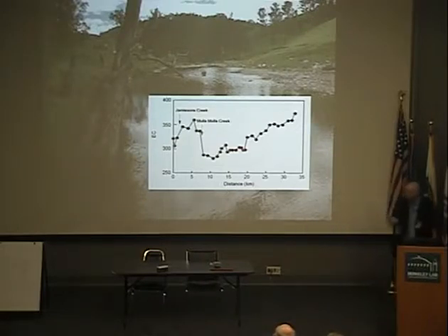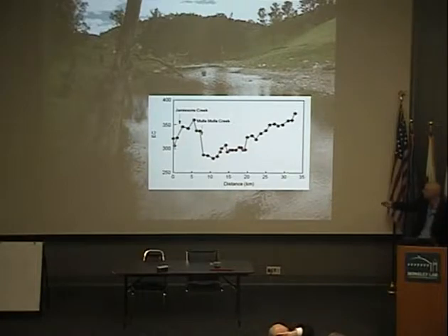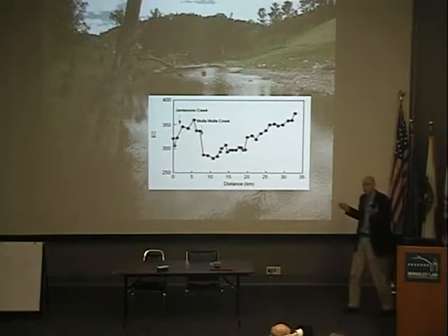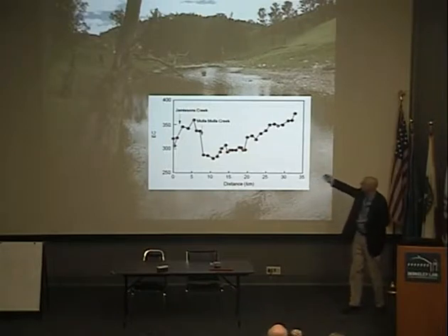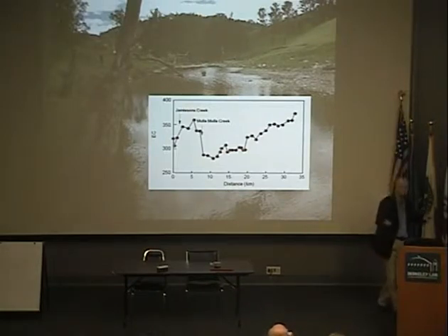This is the Cockburn River again, and this just shows the electrical conductivity in microsiemens per centimetre versus distance. There are a couple of dramatic changes where tributaries enter the river, but down here you can see there are no more tributaries and the electrical conductivity increases quite steadily. If we know what the concentration of the groundwater is, we can calculate what the groundwater inflow is from that change in electrical conductivity.